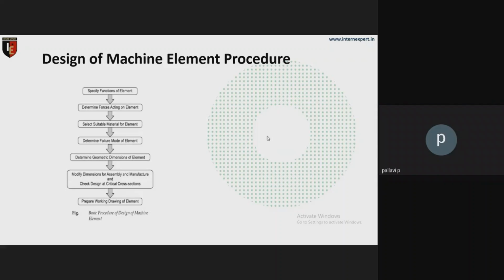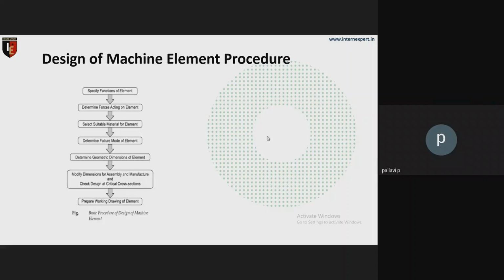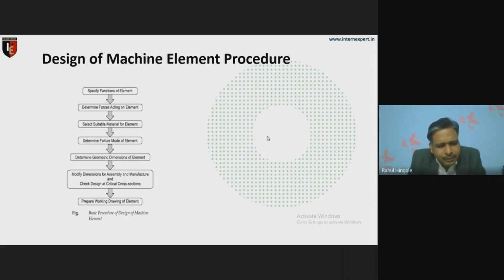Actually it deals with the meshing. When we do very fine meshing, it will take more time, because every element, every node, it has to calculate, however fine a mesh we do. If we do coarse meshing, sir, it will give a rough result and a very fast result. With very fine meshing, it will take a lot of time, sometimes more than 12, 13, 14, 15 hours also. Yes, it is good.